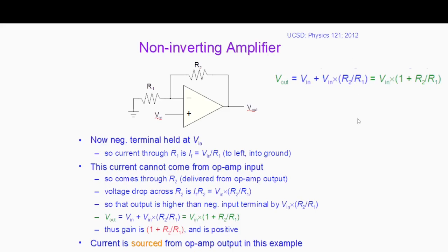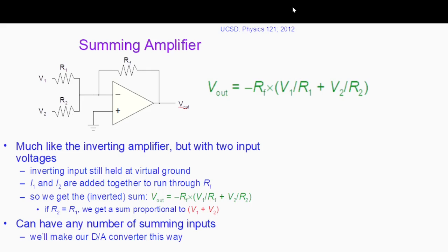Again, this is the non-inverting amplifier, another way to describe it, as we have already derived this equation, how this non-inverting amplifier equation arrives at this particular form. And this is the summing amplifier. Okay, so as you can see here, we have V1 voltage, V2, but it can be going down like V1, V2, and all the way to Vn. So all those voltages, when we do the mathematical analysis, this is what we get as an output equation. So in this case only two voltages, so V1 plus V2, okay.